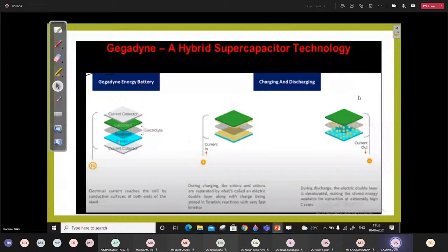And in the multiple converter configuration, both will be provided with a separate DC to DC converter. The advantage is that you can control both the sources, and you can have different voltage ratings and power ratings of the battery and supercapacitor. And here the highly varying UC voltage can be fully utilized. But two different